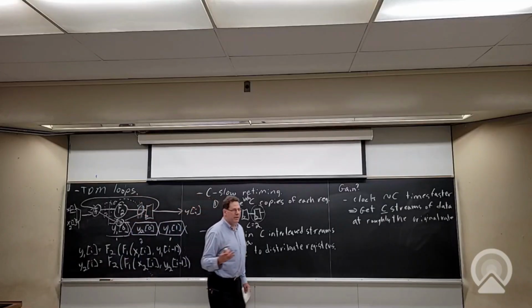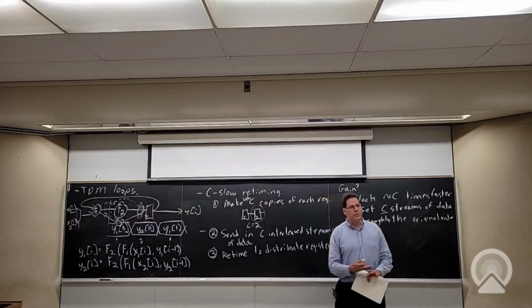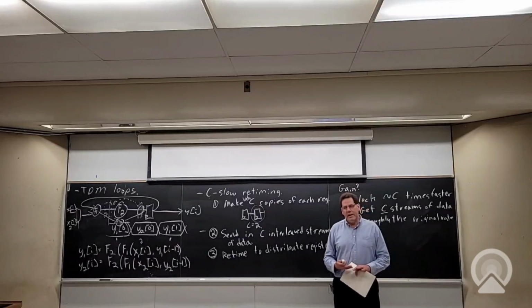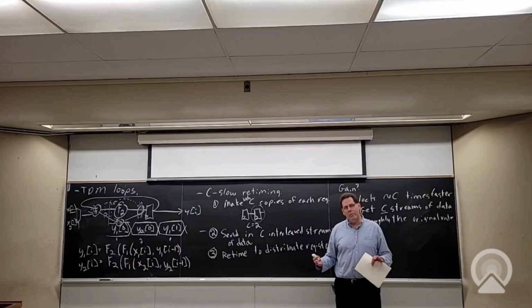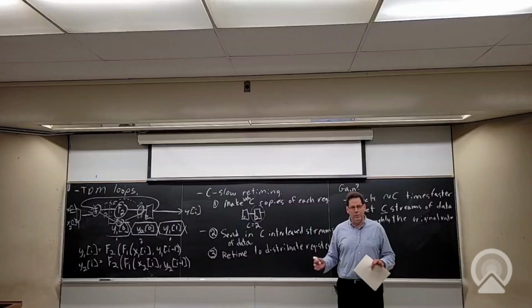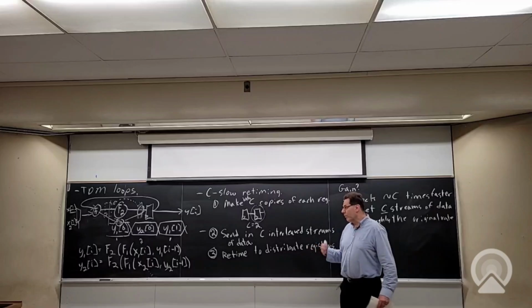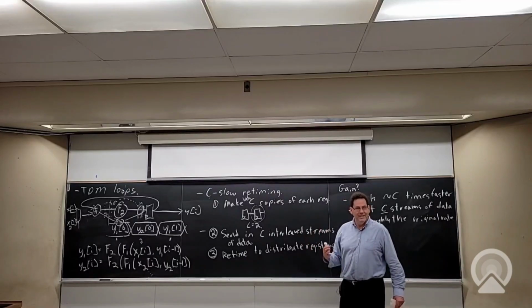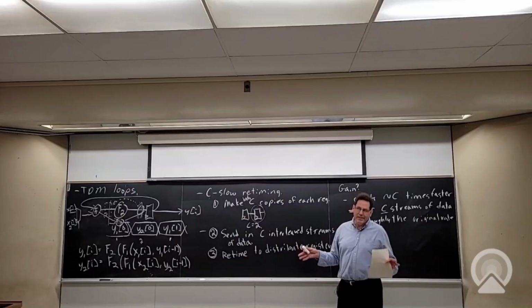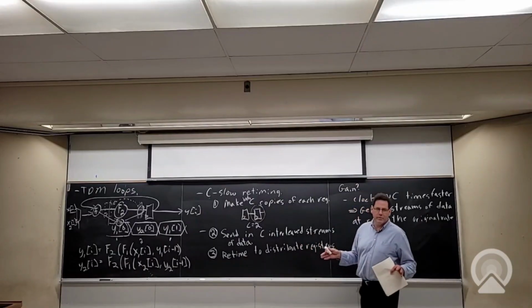So you've duplicated the register, you have a placement, you have to reinsert those registers into the placement. That's disruptive, okay? So you now might not get them where you want, which means the retiming might just be unsuccessful, or it might make things worse, or your CAD tool might take forever. And Quartus will actually do a little more of this after routing. Okay, so placement has, like, in the latest devices anyway. We'll talk about this later in the course.